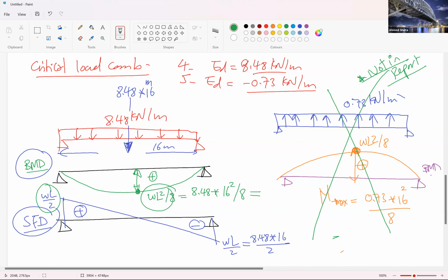No, because you said the important thing. B1 is an external beam or roof beam, so it is subject to upward and downward wind load. But for B2, it is an internal beam, so there is no wind. Yeah, because all this extra stuff is only for the external, the roof beam.